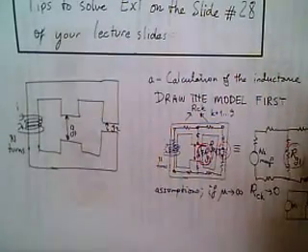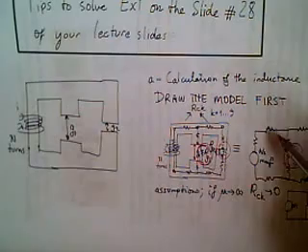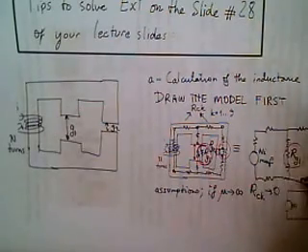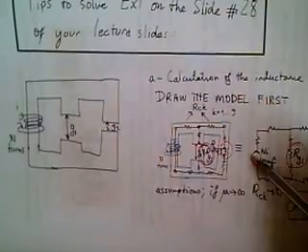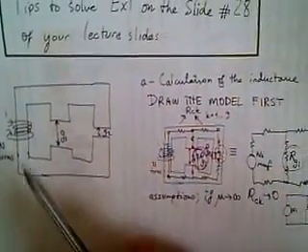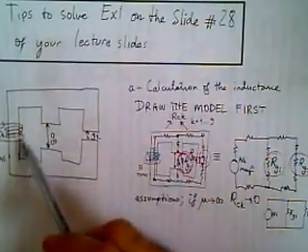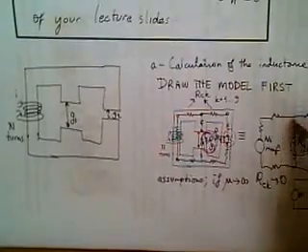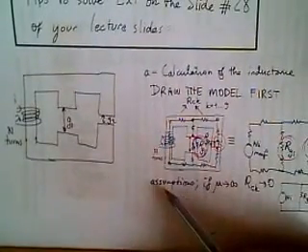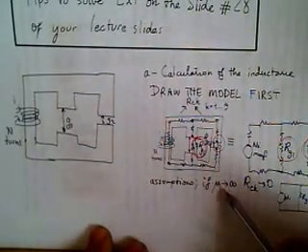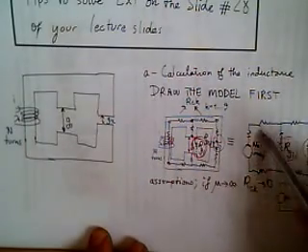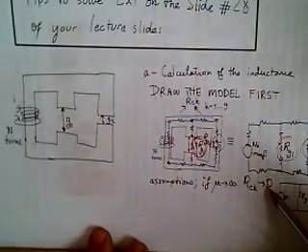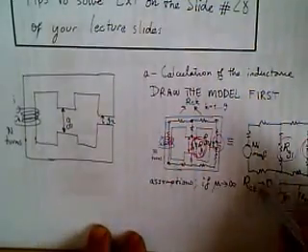So the complete model, to be solvable in the problem, will consist of some core reluctances depending on the geometry and permeability of the material, and a magnetomotive force source. The source is the N-turn coil, and when we assume the permeability is very high, the core reluctances will tend to go towards zero.